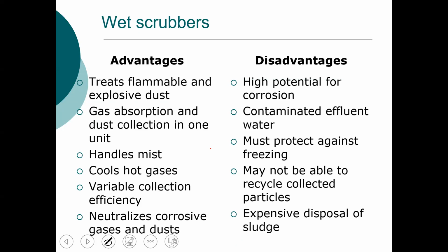It can handle gases that include a mist, so moist gases. Remember, we mentioned that on a fabric filter, if you have condensation on the inside of the filter, then you have greater potential for corrosion, and that results in a deterioration of that fabric. If you have very hot gases, the water cools that. So in terms of subsequent treatment, you've already cooled the gas, and you don't need an additional process in order to cool that gas.